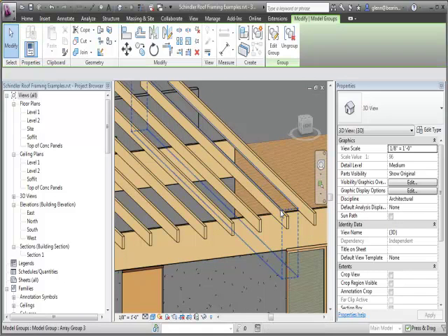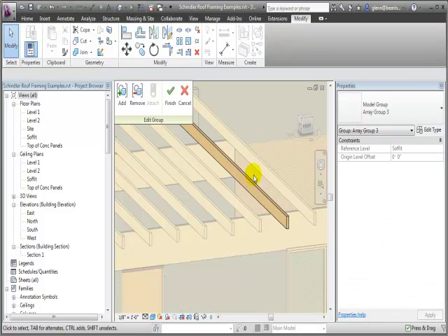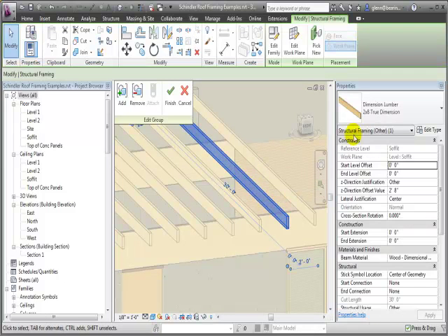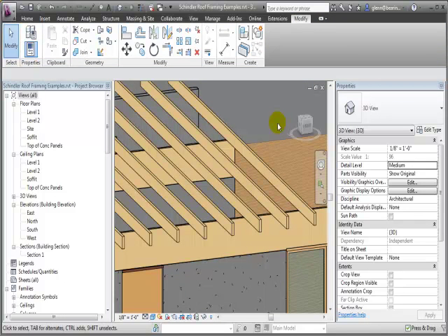So in this case, I just have a bunch of different little structural elements. I have them all arrayed together right now to make the spacing easier, but you'll see they're all 2x8s. The top of them are really 2'8" above the soffit wall because the bottom was at 2 feet above. So let's just go ahead and close it up, and we'll think about how we can extend these. The idea is we're going to put a roof on top of this, then fill in the gap between the roof and the top of these joists.